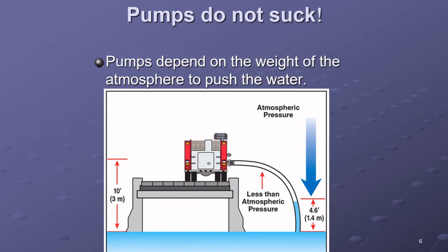If I look at how this works, I have a pump right here in the middle of this truck. And that pump is spinning and trying to push water because pumps don't suck, right? So my pump's pushing water, and on the suction side, I know pumps don't suck, but we still use the term all the time. On the suction side of that pump, it's creating an area of low pressure. Well, my atmospheric pressure out here is pushing down on my water source.